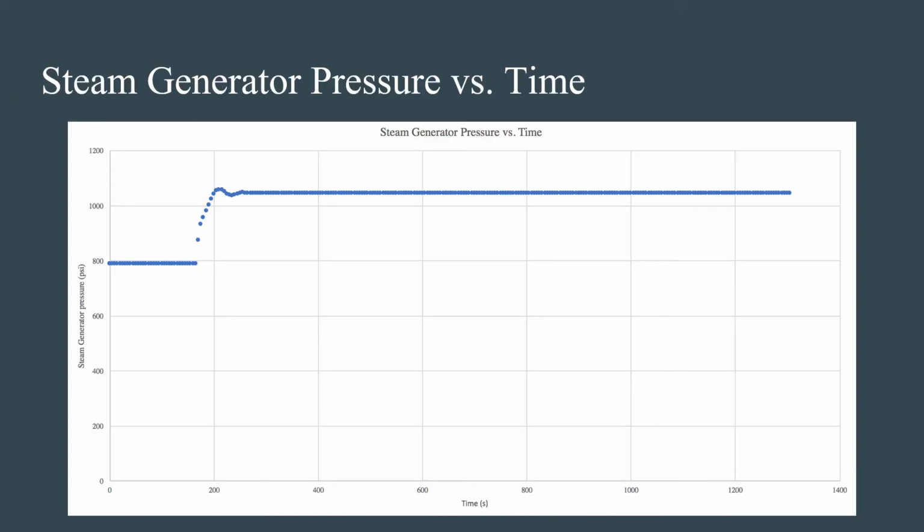Here we see a different trend. There is an increase in the pressure of the steam generator. The cause of this increase and then the constant pressure is because the decay heat from the core causes pressure buildup. In a reactor trip, the fissions may stop, but the fission products are still around and radioactive and will produce heat due to radioactive decay no matter what.